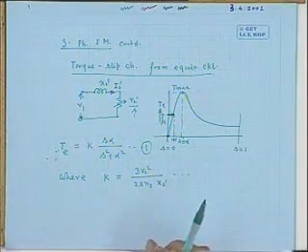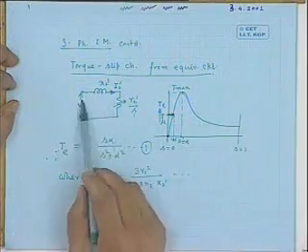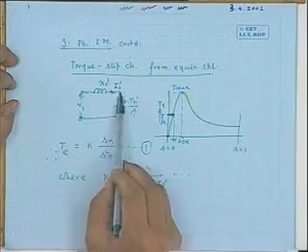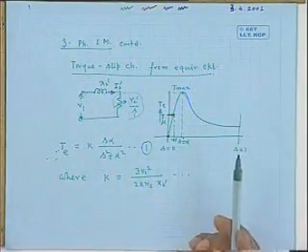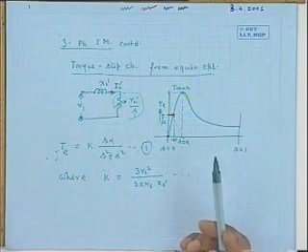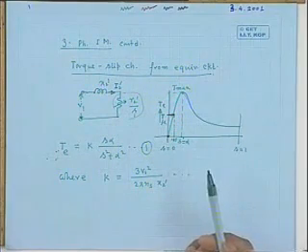That's why when torque is expressed in watts, it is written as synchronous watt, as I told you earlier. Therefore, torque will be maximum when power in this resistance will be maximum. As simple as that, because that power divided by 2 pi ns will give you the maximum torque developed.